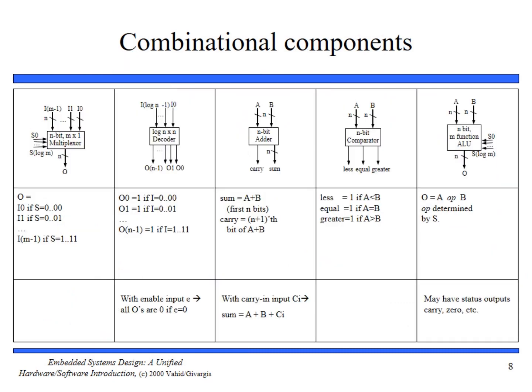So in this figure you can see 1, 2, 3, 4, 5 basic combinational logic components. Although we can design all combinational circuits in this manner, a large circuit would be very complex to design. For example, a circuit with 16 inputs would have 2 raised to the power 16, or 64k rows in its truth table.